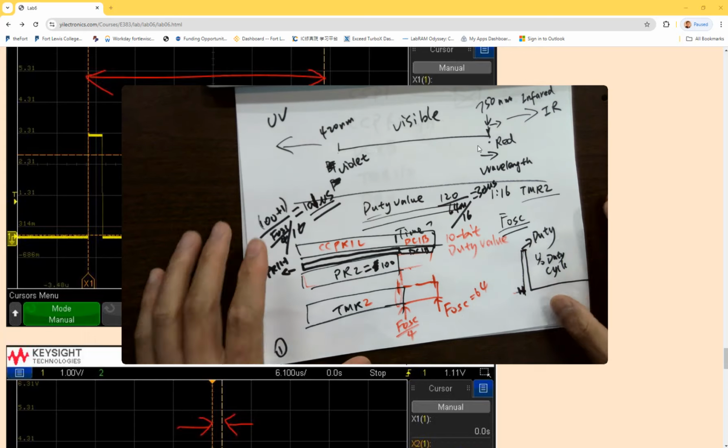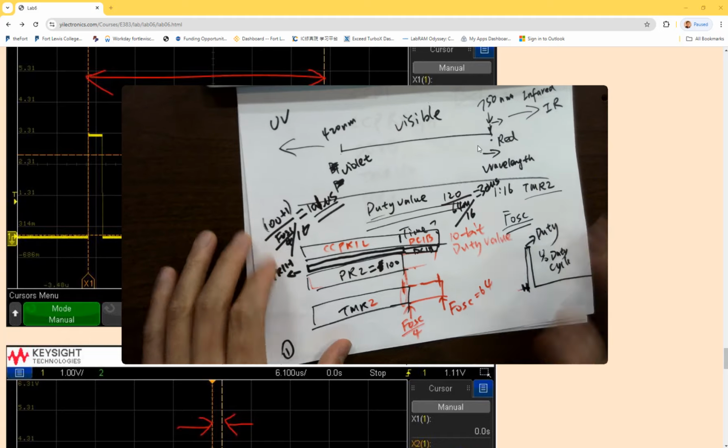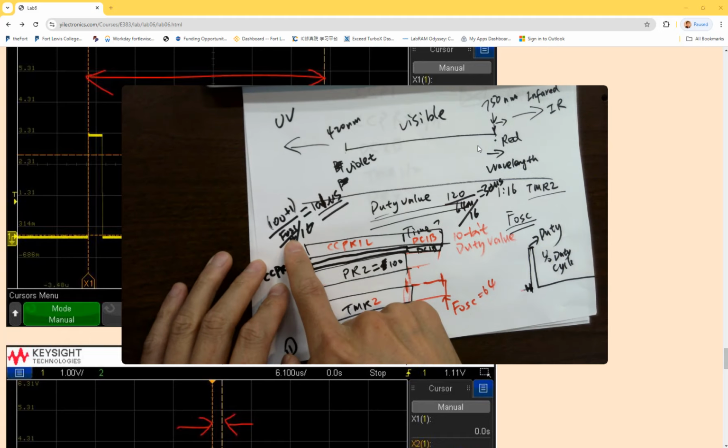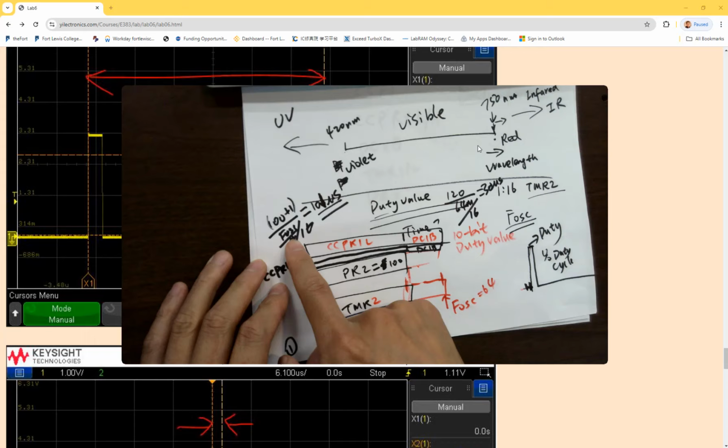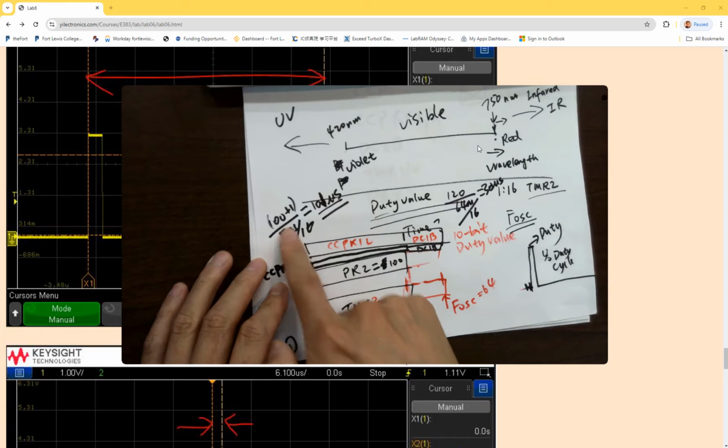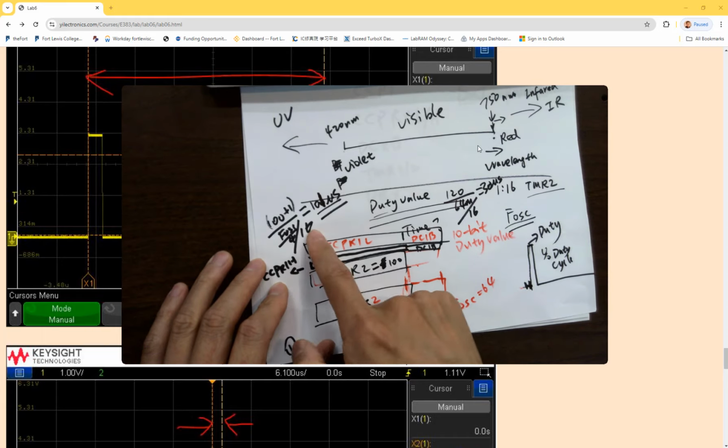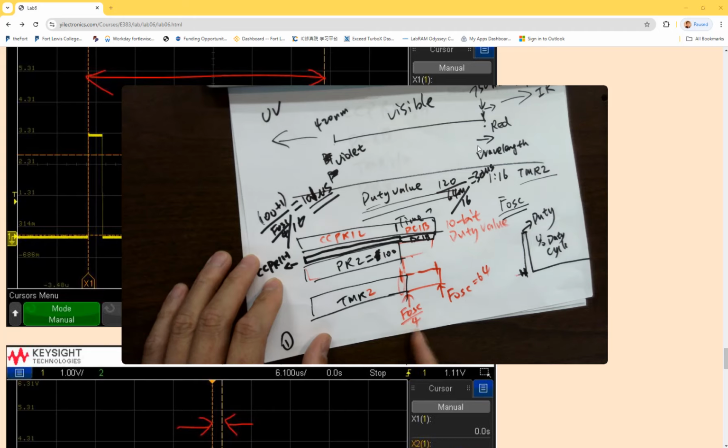Where is the calculation for the period? Here. Okay. Period. Yeah. You'll give us a number of counts to determine the period, right? Yes. Yeah, with the counts. Counts plus 1 over FOSC divided by prescale. No. FOSC divided by 4 divided by prescale. Because that's for timers.